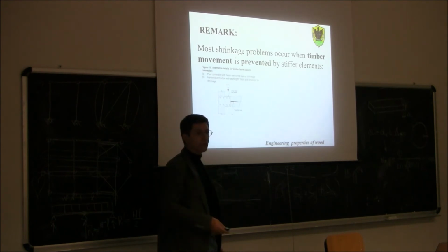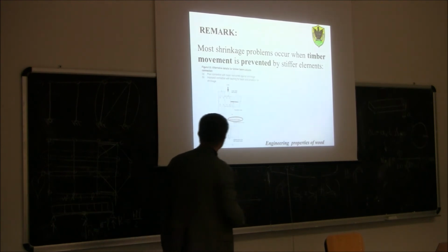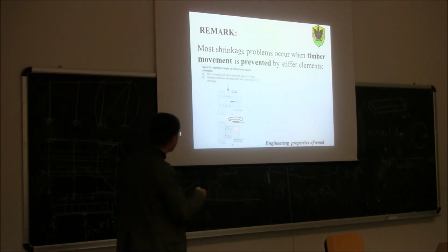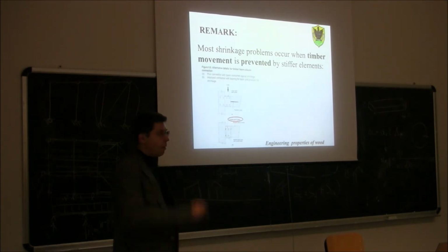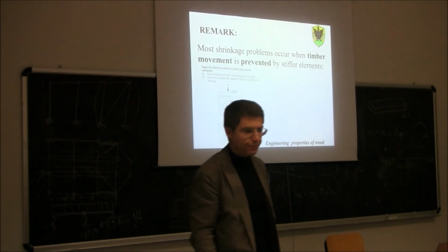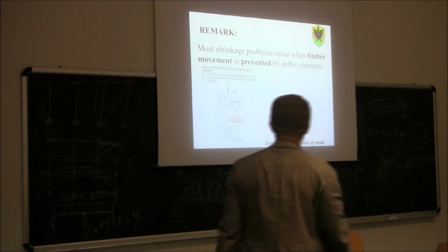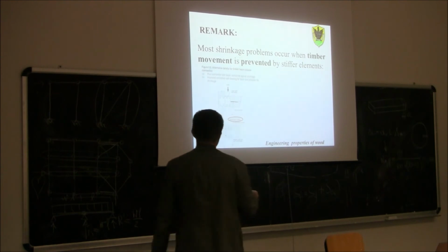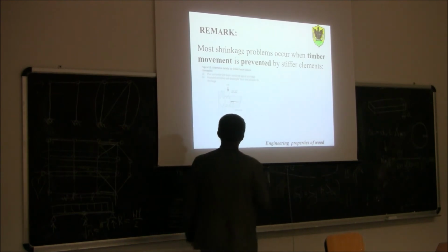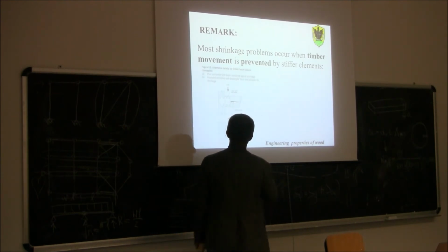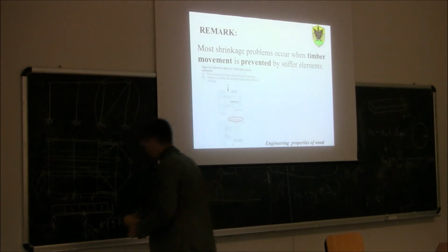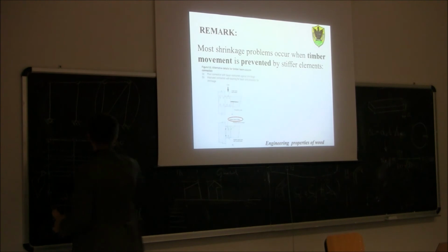How can we make the wood free to move inside the connection? We need to use ovalized holes or slotted holes in the steel. So basically, as you can see here, in the steel plate, we will have an ovalized hole.